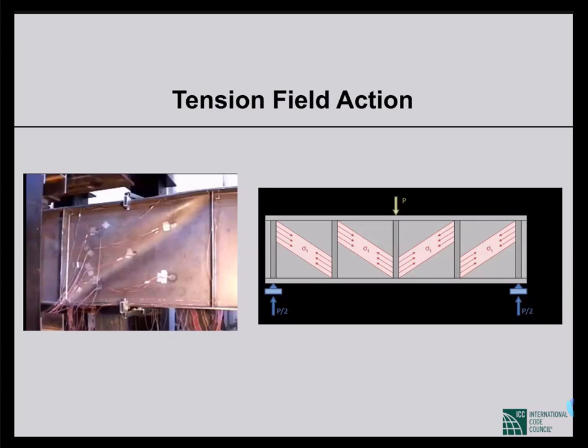So even after buckling, the tension action will act like a bracing and will still continue to take load, because this part, as you can see shown in the middle diagonally on the left side in a test sample, is buckled, but in the middle you can clearly see something like a bracing. So that will still act like a bracing.